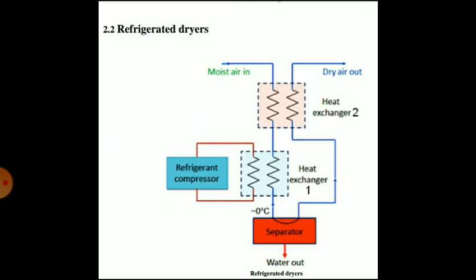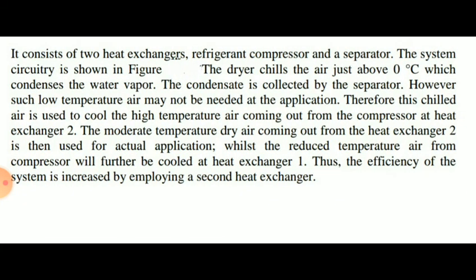Then dryers. These are the refrigerated dryers. In the diagram shown, it acts as a heat exchanger to cool the air. It consists of two heat exchangers, a refrigerant compressor and a separator.